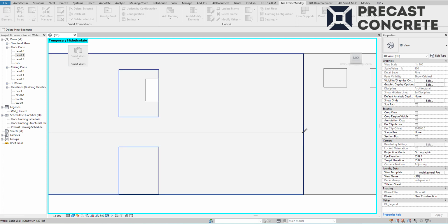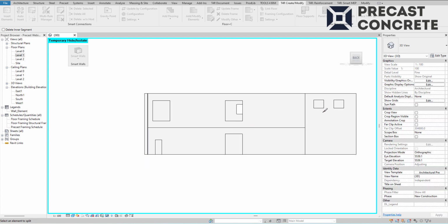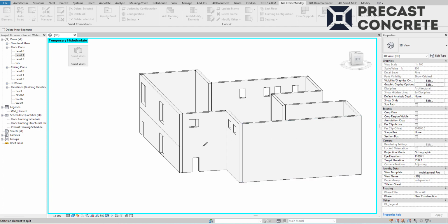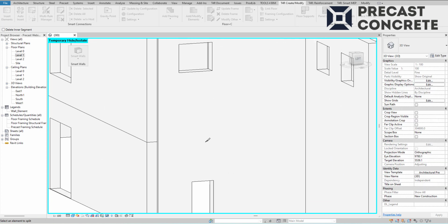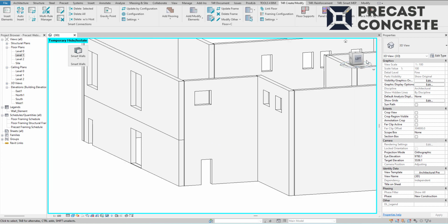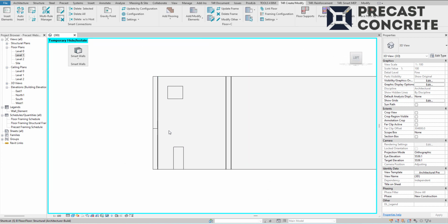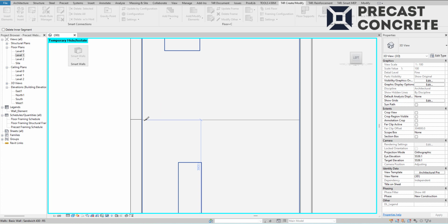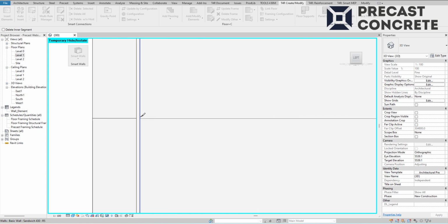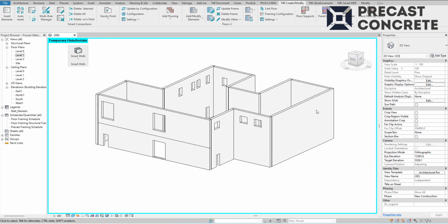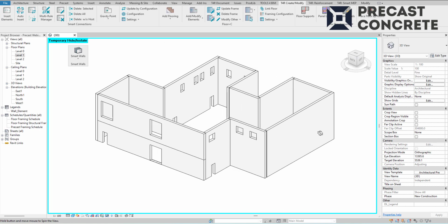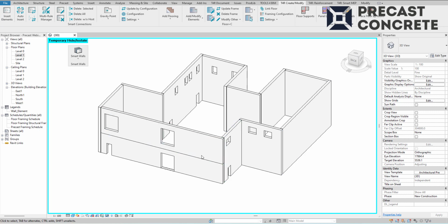Once I'm done with this wall, I need to move to another wall. I need to again select a certain camera angle, because I can't do that at this point. I need to again select left view, pick the split element tool, and accurately split this wall element. And I need to do that for all of these wall segments using this native Revit workflow.